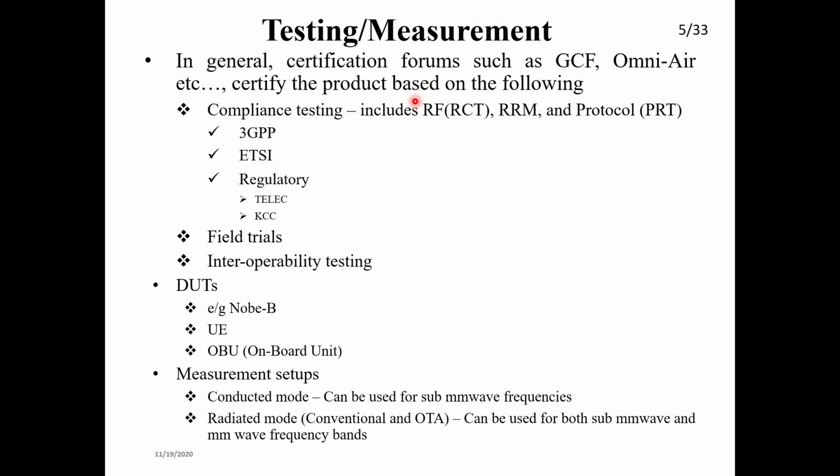As we said before, conducted mode can be used only for sub-millimeter wave frequencies, because the components are much more expensive and complex. Handling is also very difficult, because if you are not applying a particular torque while tightening, for example tightening by hand, the connector can break from the cable. Also you cannot have long cables, but in a real-time setup you would need a lot of cables, and it becomes a very tedious problem. That's why we cannot use conducted mode in millimeter waves.